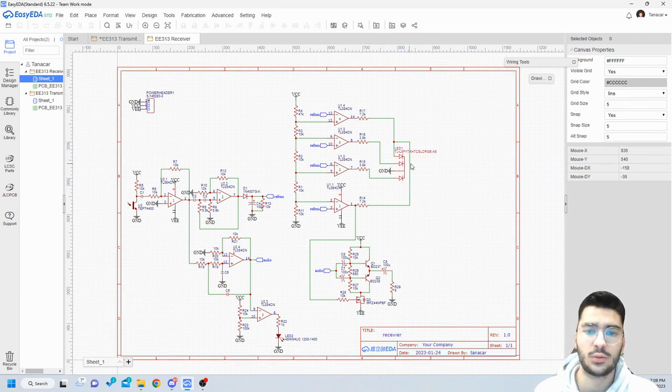We control the blue channel with two op-amps, and we control the other two channels with just one op-amp. They are simple. With two op-amps, we do a voltage division, and that's how we open the blue channel right in the middle region, and then close it back when we are at the most powerful state.